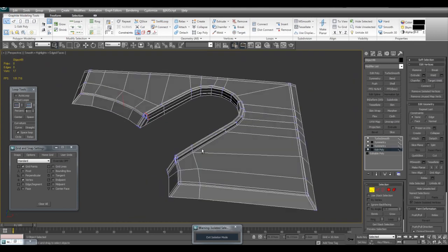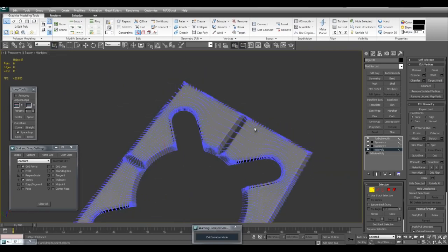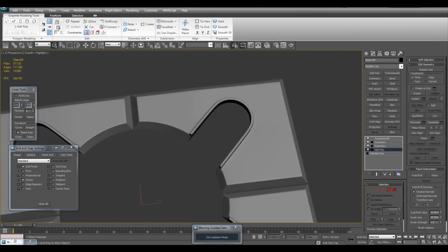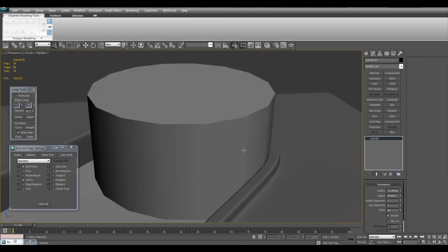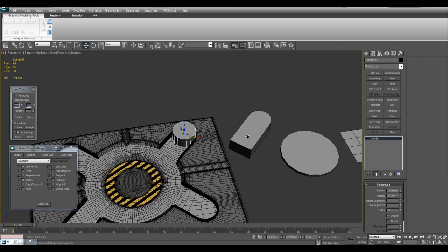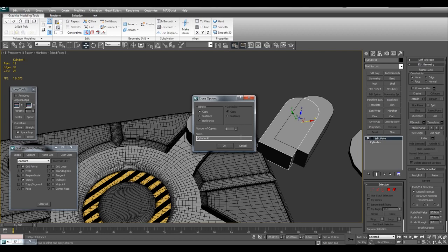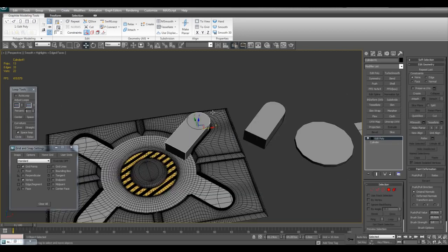But this is an example of how you can recycle various parts. Just bring that cylinder back in here and use it carefully like this, and you've got yourself a nice hard surface shape. And because I made a clone of it, we still have this cylinder here. Or what I can even do is select this one, copy it, maybe as an instance, a copy for now. Press Alt A and align it right here, and it's right back here.